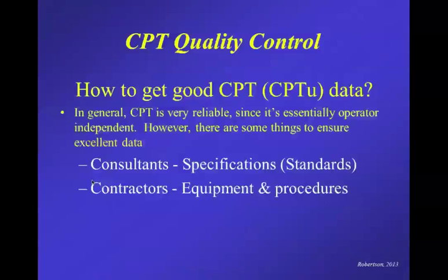So how do we get good CPT or CPT-U data? In general, CPT data is very reliable. I mean, that's why the test is so popular, because it is a generally reliable, repeatable test. And that's because essentially it's operator independent, so it doesn't matter who's doing the test, providing the equipment is maintained according to the standards, and the procedures are carried out according to the standards, and you typically get good reliable data.